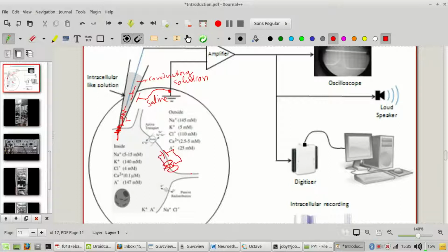So in effect this is connected like this, right? There are combinations of resistances and capacitances, in series, parallel, and so on, in this configuration, and depending on the position of the electrode and so on, these resistances can vary. The surface area change where you are recording from, all that affects this capacitance and this channel conductance.